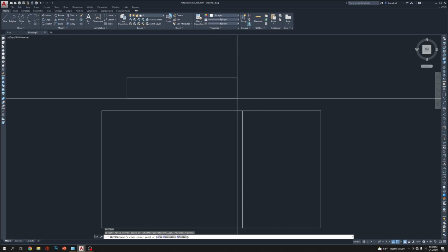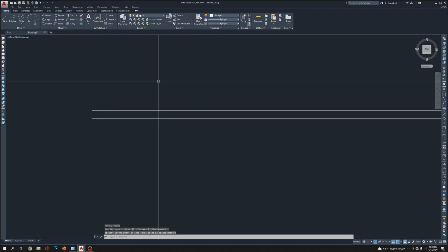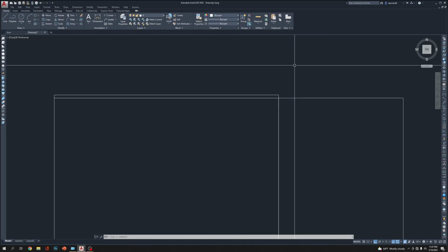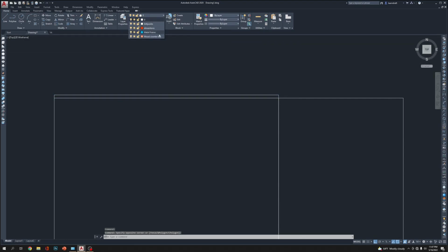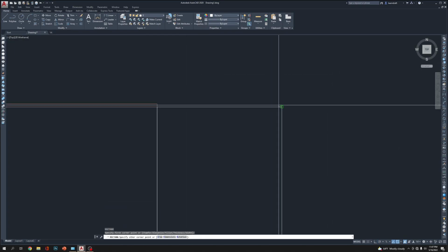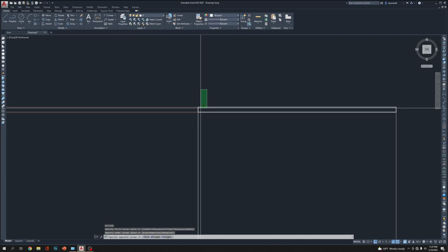D, enter. It's going to be 36 by 0.5, which is 1/2 inch, click, move from here to there. It's going to be a line, no overlapping on the right or left. Here is our tabletop, this one. I'm going to select it, click it here, make it wood countertop, and the other piece is going to be here. So I do not need more dimension because I have this corner. I'm just going to click from that corner to this corner, select it, then go there, change the layer, wood countertop.